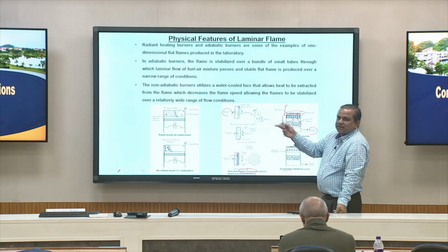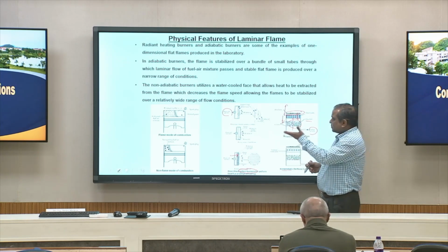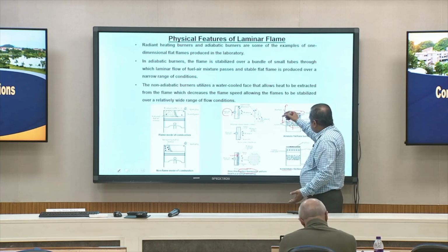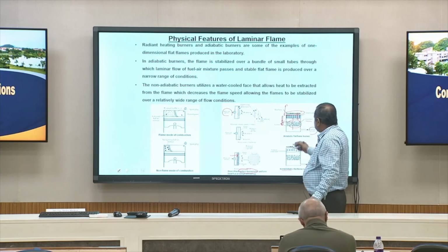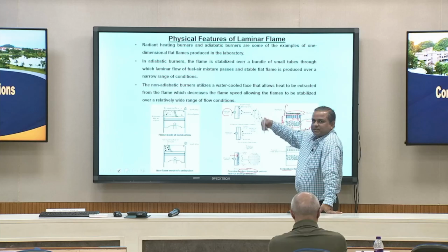Propagating back means if that condition is not maintained between the charge, gas and flame velocity, the flame goes back and can directly come to this fuel air charge, that means the flame is moving back. This kind of situation creates an explosion. So we call this a flashback.